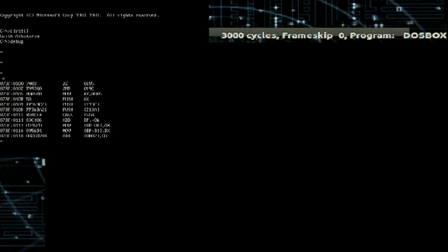Memory addresses. And the 073F is a memory address. The 0100 is also a memory address. That's the segment, and one is the physical address. And the 7403 is what? It is the opcode, the value for the jz command. That's a jump on zero command, jump 0, 010F. That's what the code is.